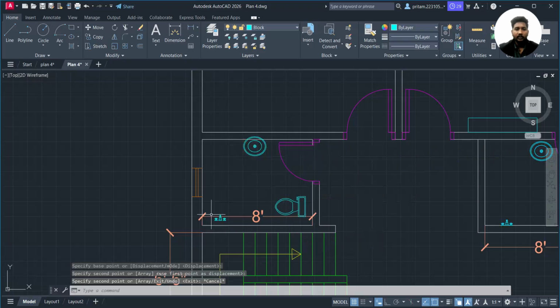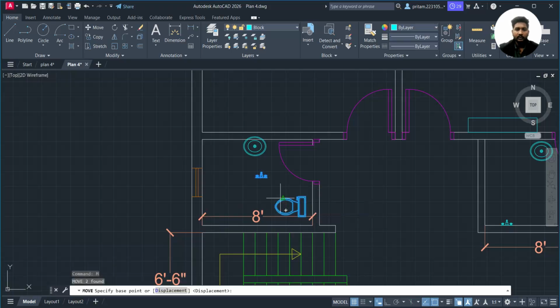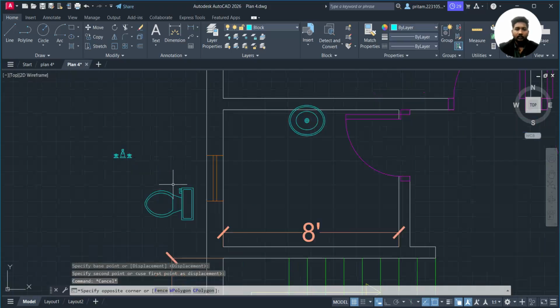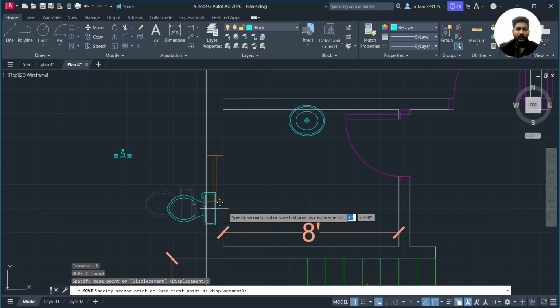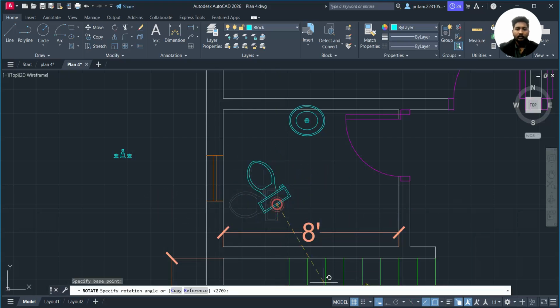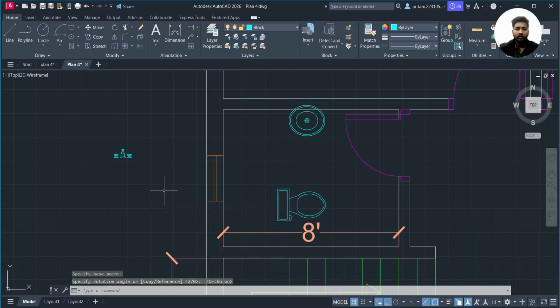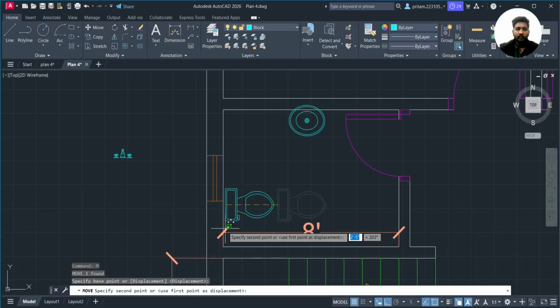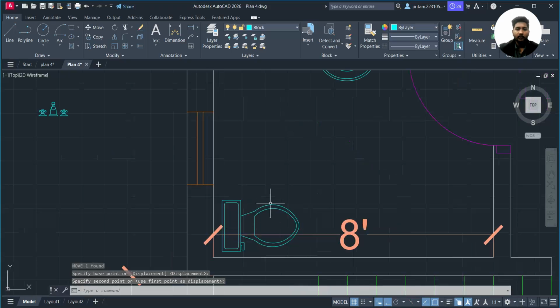Then after we will just drag this part, move it like this way here. Then choose this toilet part here. Then just rotate it, arrow, on this ortho mode, drag it backward here, and place it here wherever required. Okay, you can place wherever required.